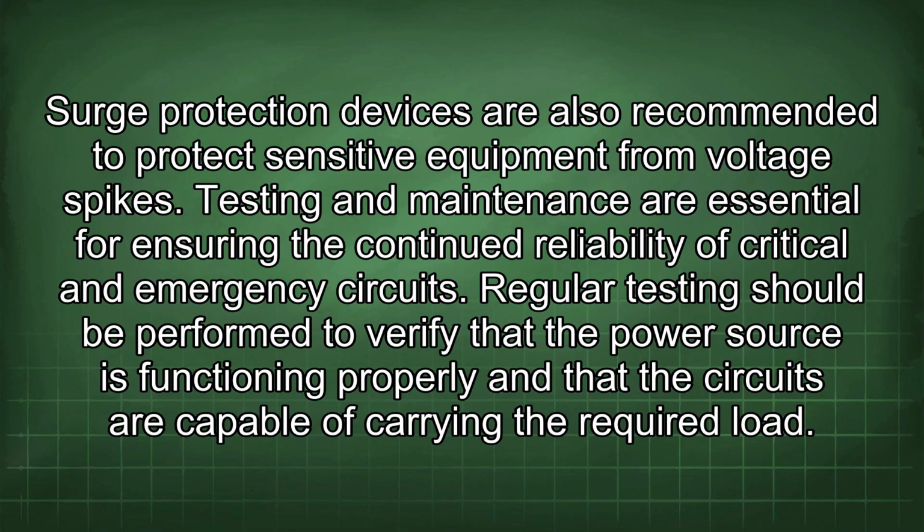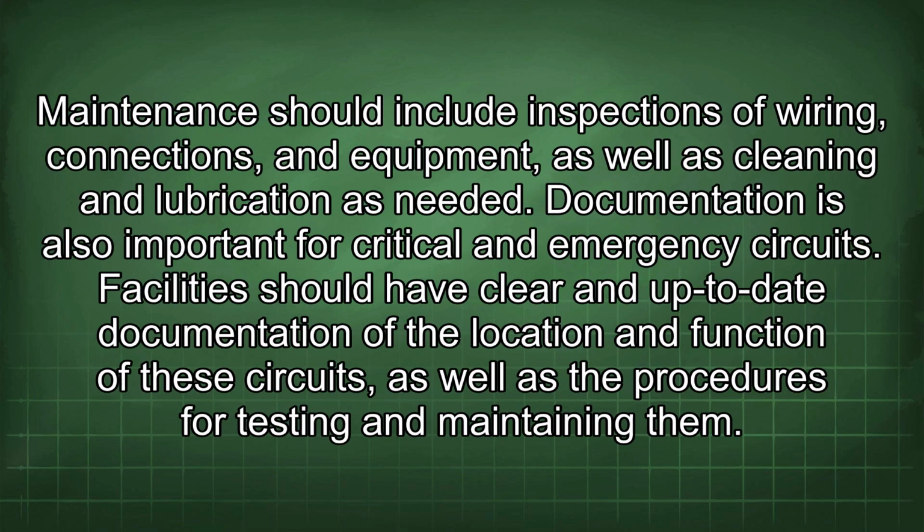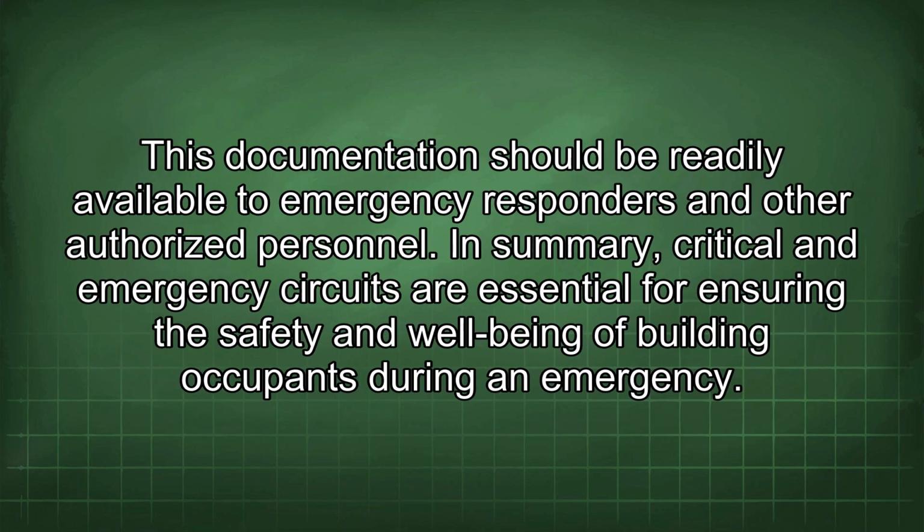Testing and maintenance are essential for ensuring the continued reliability of critical and emergency circuits. Regular testing should be performed to verify that the power source is functioning properly and that the circuits are capable of carrying the required load. Maintenance should include inspections of wiring, connections, and equipment, as well as cleaning and lubrication as needed. Documentation is also important for critical and emergency circuits. Facilities should have clear and up-to-date documentation of the location and function of these circuits, as well as the procedures for testing and maintaining them. This documentation should be readily available to emergency responders and other authorized personnel.